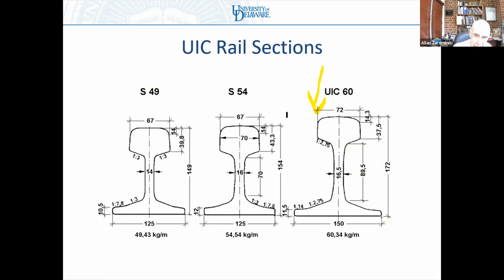If I apply my vertical and lateral load here, and why am I applying it here? Because in a curve, this is where my wheel flange is. My wheel flange is exactly over here. So I have my lateral load here and my vertical load here.